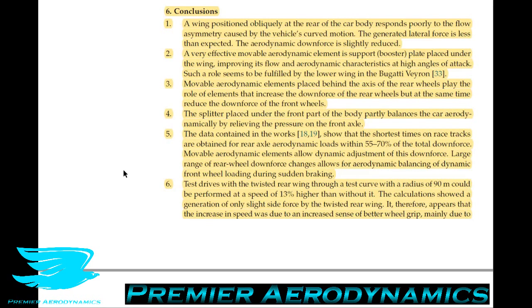It depends how stiff the suspension is, but if it's quite soft and even if it's somewhat hard, you'll still get a little bit of play forward, and that actually lowers the front axle a little bit more and also changes effectively the angle of attack of the car. So the car is tilted forward a little bit, which does change its aerodynamic performance a little bit. By having these different aerodynamic components, you can change that and sort of alleviate that in real time.